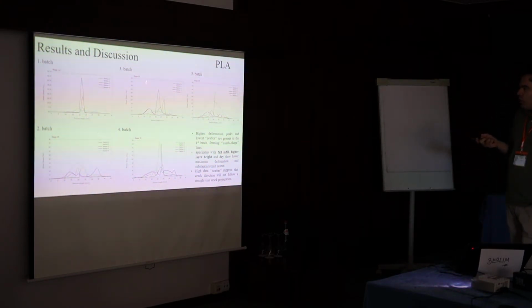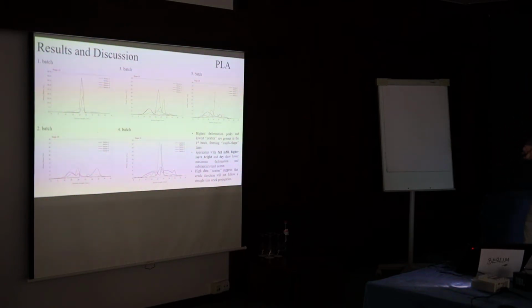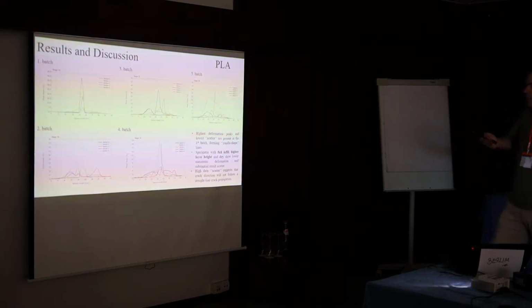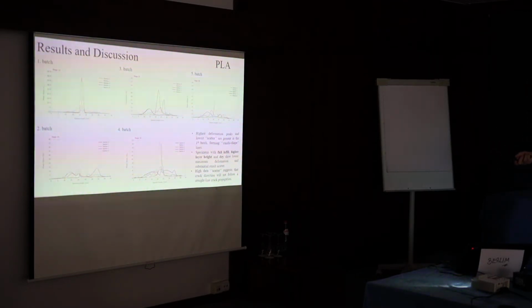Compared to the 100% infill density batches, here we see lower deformation values but much higher scatter along these section lines, showing that there is some deformation on the sides of the expected crack propagation path. So probably these specimens could have some angulation in the crack path.